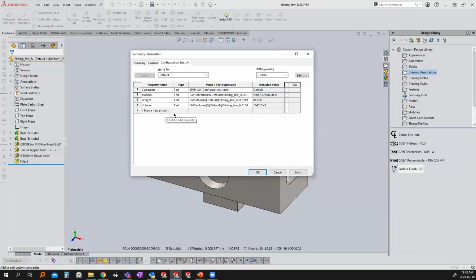One thing you can try to do to alleviate some manual input is try and bring it back to a SOLIDWORKS automatically generated property. So something like my comments, for example, look at my configuration name. So if I have, say, a screw with several different size configurations, as long as I rename the configurations, which I should be doing anyways, I get the appropriate comment or description or whatever that may be classified as.